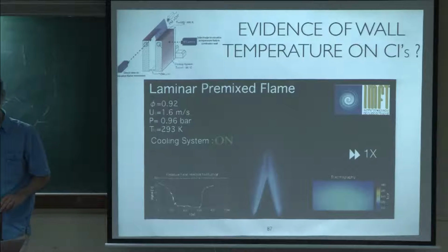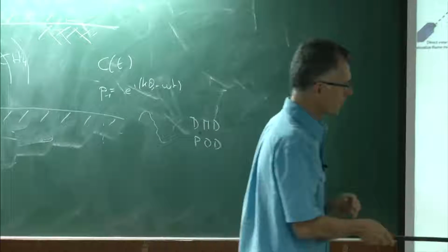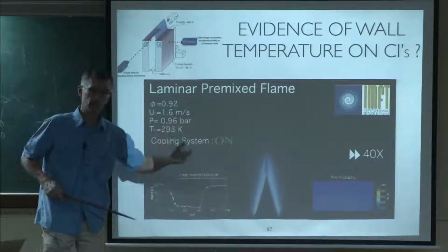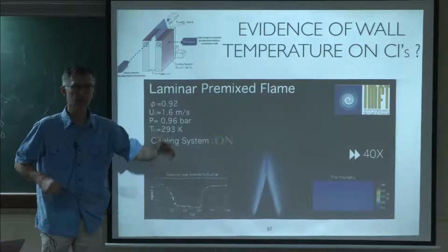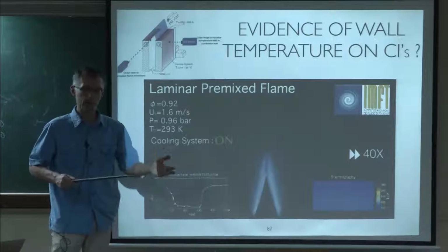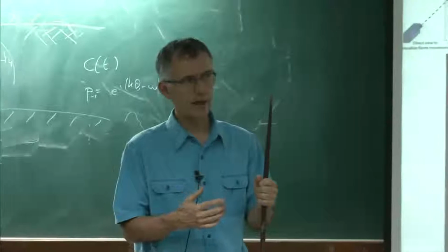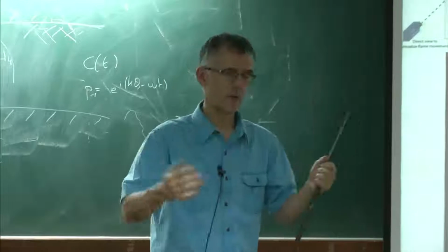So if you think about that in an engine, if you take a gas turbine, you would start it. When the walls are cold, it would oscillate. And then a few seconds later, maybe 30 seconds later, it would stop oscillating. And then you can operate it. This is also why certain engines make noise at cold start. And then if you wait long enough, it disappears.